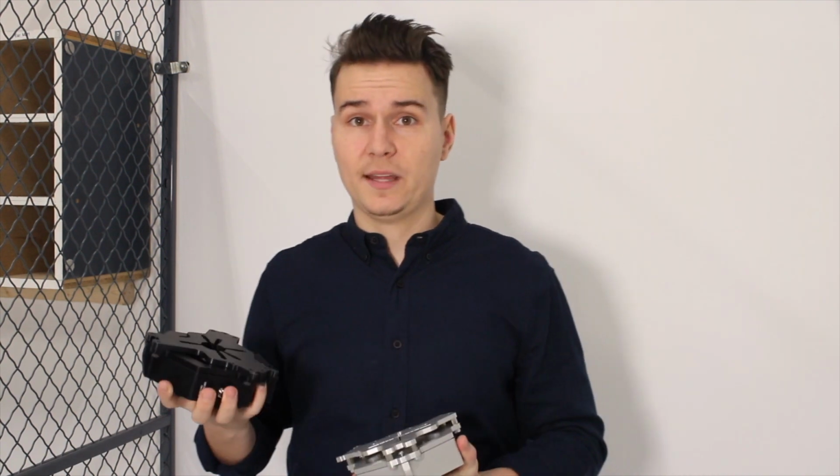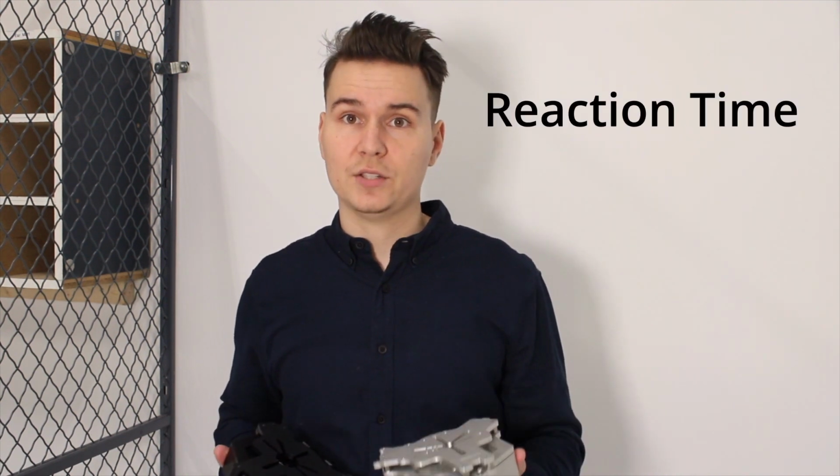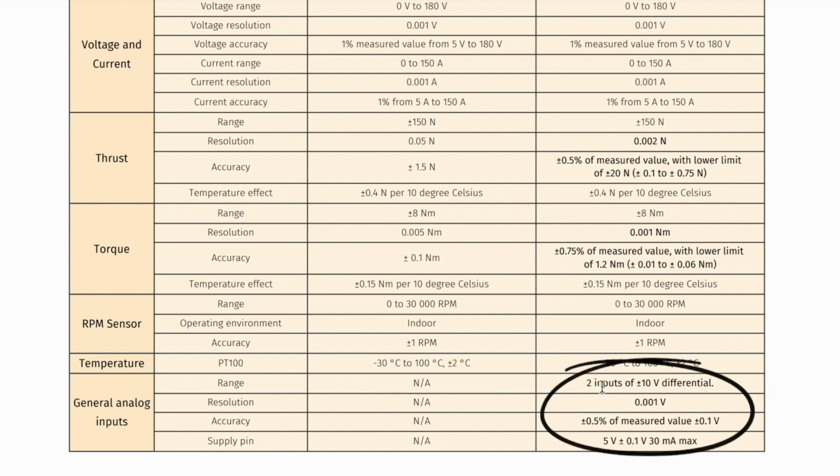The 1000 Hz sampling rate allows you to go a step further and characterize things like torque ripple, the effect of propeller wake on obstacles, and reaction time. It also allows you to perform in-depth analysis of current, voltage, and vibration. In addition to the high sampling rate, the Pro version comes with two analog inputs where you can connect any analog sensors of plus or minus 10 volt differential, like a pressure sensor or an acoustic probe.